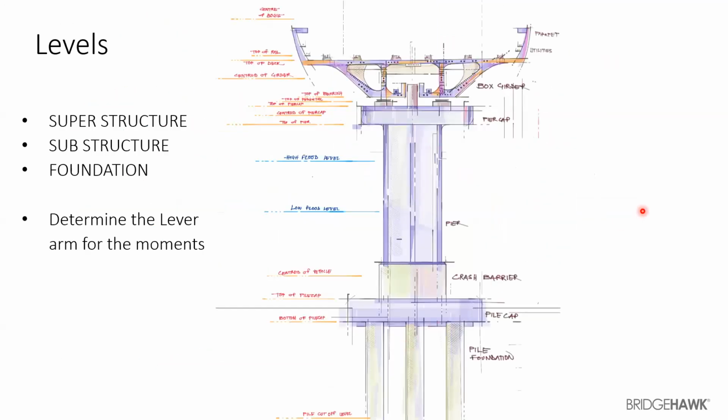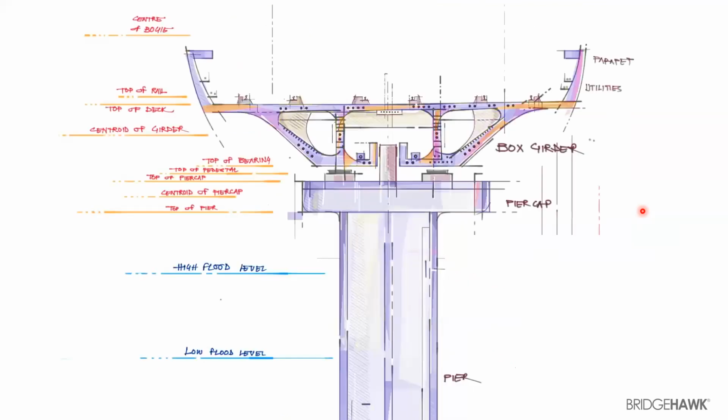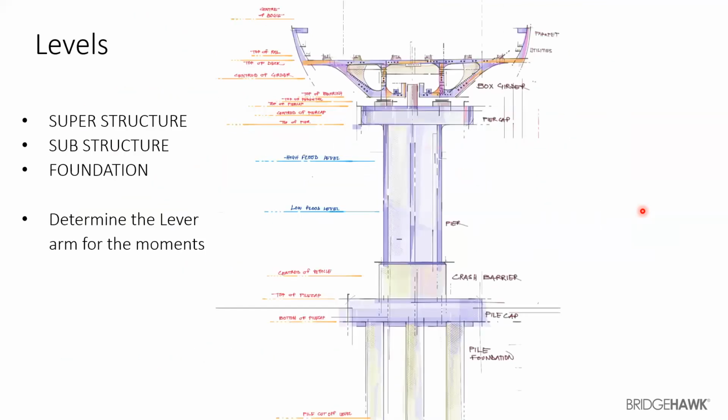So once you know these levels are important, what you'll basically do is create a table in Excel, and start to input the values in that table. Okay. So once you have these values with you, and many times if you know the dimensions of certain components, you can directly have that table with you. This is a very important tool for you, and as a reference, you can add up your values to create the lever arms for your moments. Okay, so you'll be creating a level table before you start calculating the moments.